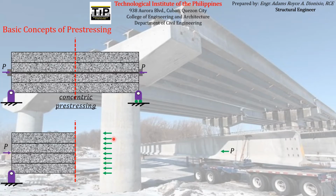the cross-sectional area, with a magnitude of, from strength of materials, we know that stress is equal to force over area. So if this is the force, and if we call the cross-sectional area simply A sub C, area of the concrete, therefore the magnitude of this uniform stress due to the axial force will be force over area, or P over A sub C, the cross-sectional area of the concrete. So again, I have put a negative sign to indicate that this stress is actually a compressive stress. That is our sign convention.